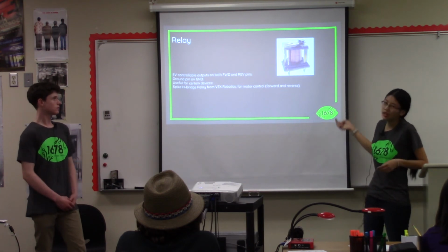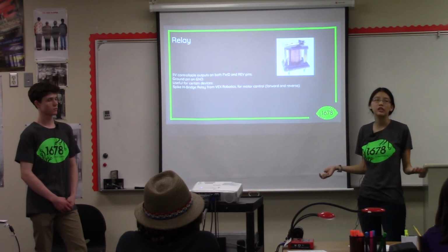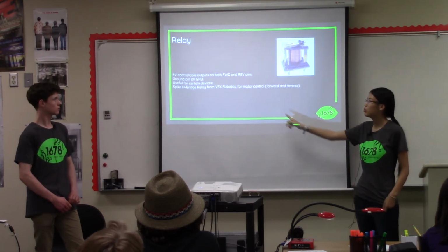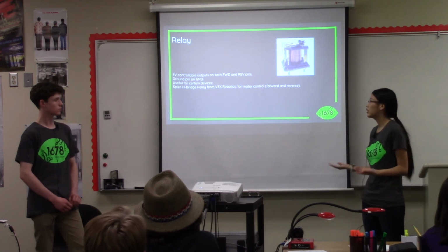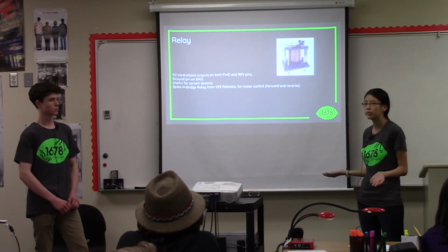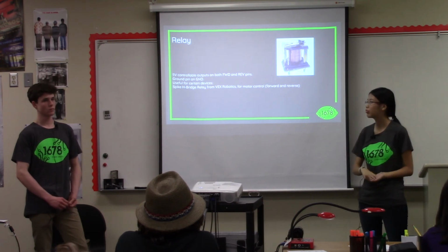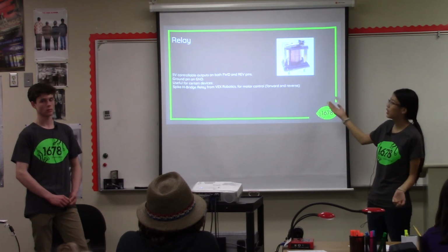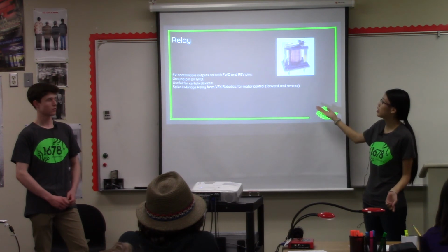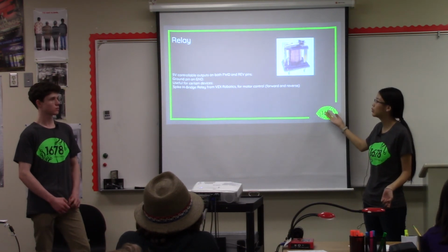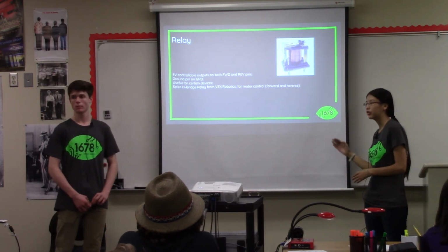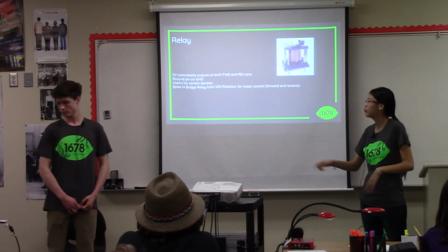So this is a relay. The most common example of relay you'll see in FRC is a Spike H-bridge from VEX Robotics. This is another type of speed controller. So this has forward, reverse, and brake. So what happens is the roboRIO sends a signal. This triggers an actual mechanical switch inside the relay, and that just either switches the motor to on, off, or brake.